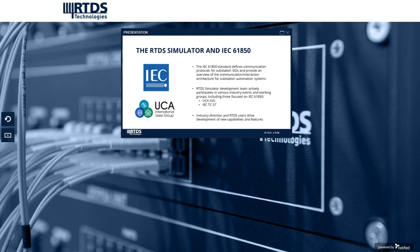Our protection and automation team participates quite actively in the industry working groups, such as the UCA International Users Group and IEC Technical Committee 57, which are focused on the 61850 standard. So changes to the standard itself, to standard compliant protection equipment, and to user requirements and use cases are what drives Rtds developments in the 61850 category. And we're really seeing an uptake of sampled values in commercial relays, and there's some precedent for it out there in substations now. So the enhancements we're discussing today are motivated by the fact that customers really need improved testing facilities for SV applications.